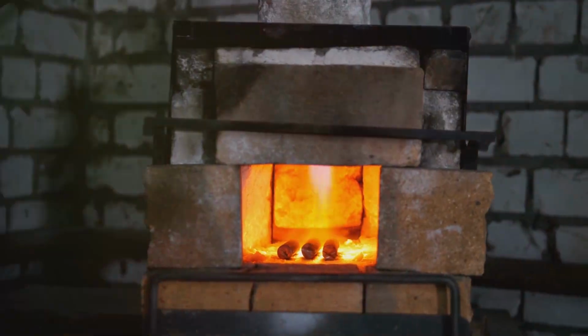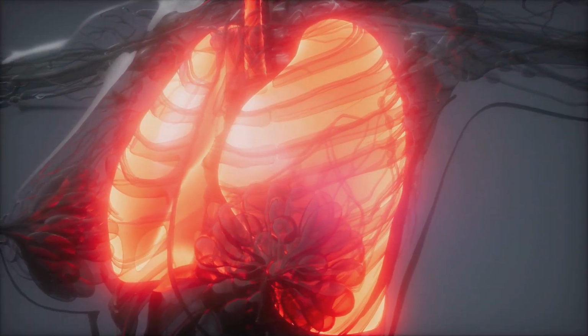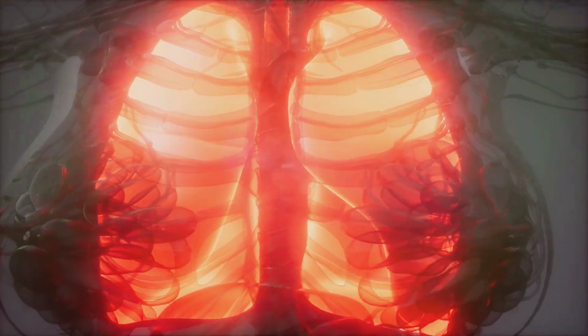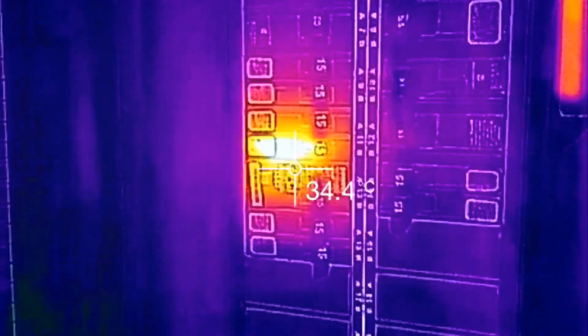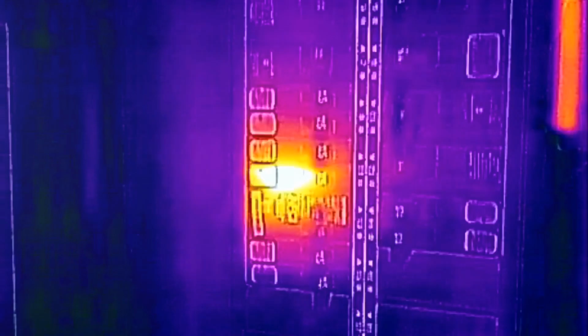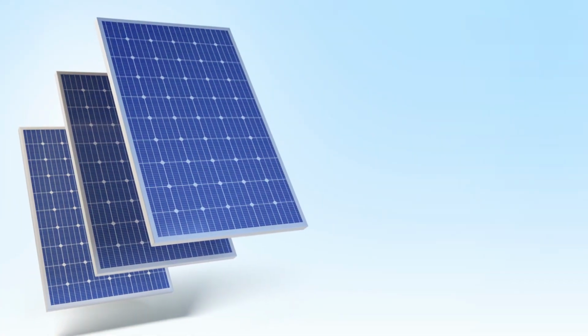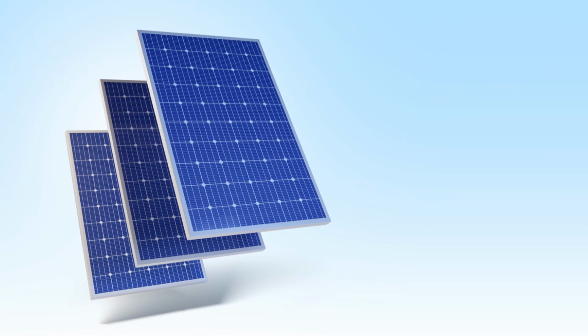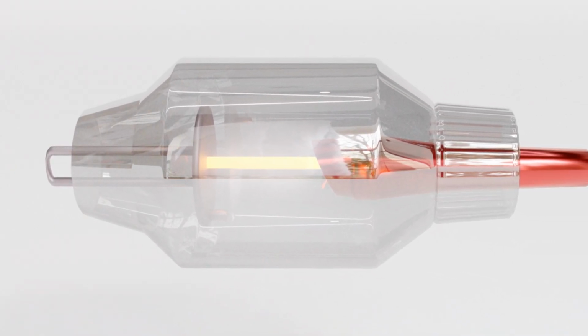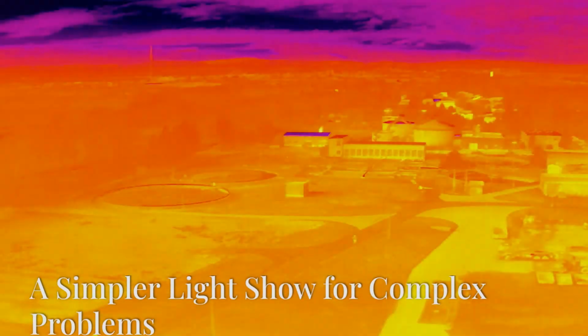DTRM is suitable for a wide range of applications, from furnaces to solar receivers. It's particularly useful when dealing with complex geometries and non-gray media, where the absorption and scattering properties of the medium vary with wavelength. However, DTRM's accuracy depends on the number of photon bundles used and the angular discretization, similar to the DO model. Overall, DTRM provides a robust and versatile approach to modeling radiation heat transfer in participating media. Its ability to handle complex geometries and non-gray effects makes it a valuable tool for many engineering simulations.